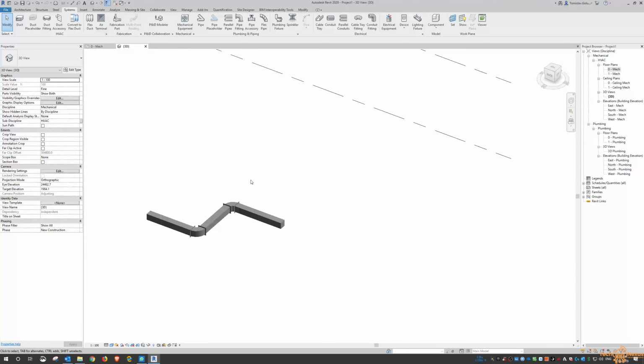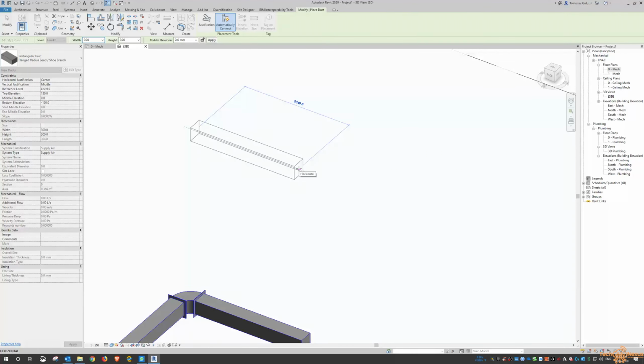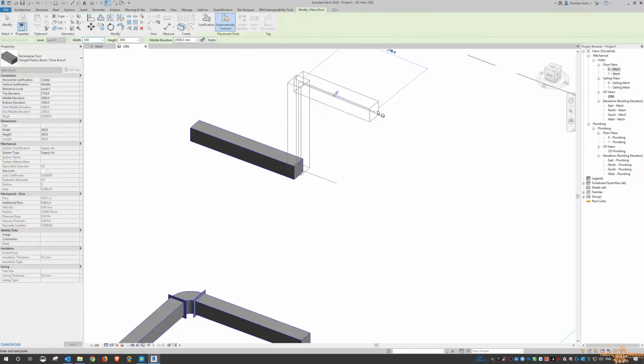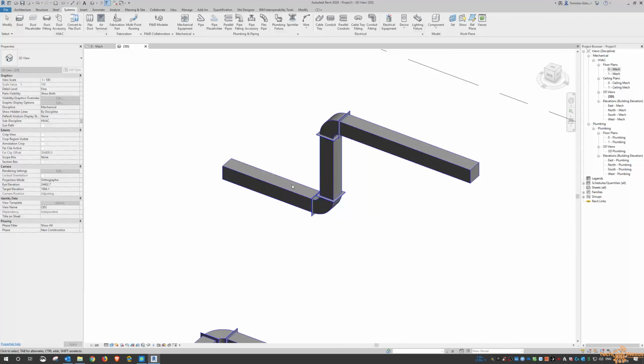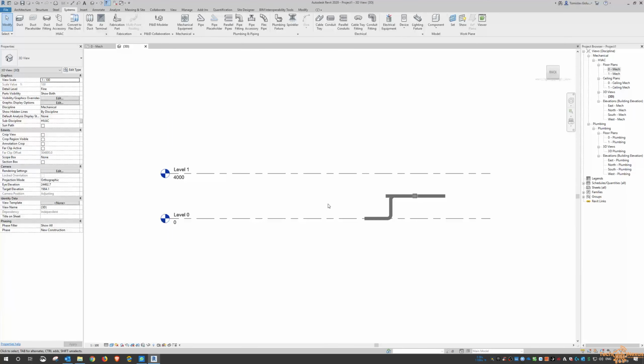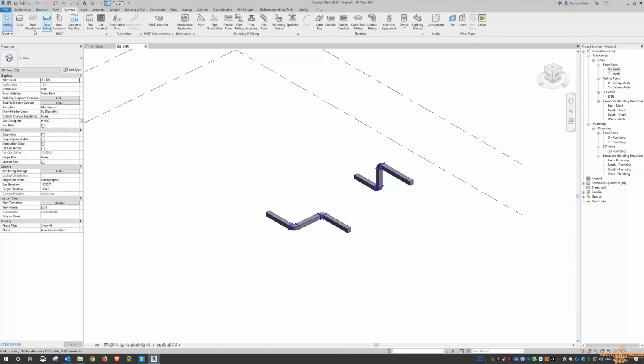If you wanted to do the same thing but go vertically, it's a little bit of a change. Now let's put this at 0, and then when I do run my duct, I'm just going to run it, let's say 2 meters, and now I want to go up 2 meters. So I change the elevation, and you can see it puts the vertical run there, and it puts me back into a horizontal. So now you can see I've got my flanged bends going in the vertical rather than the horizontal. Okay, so that's the ductwork.